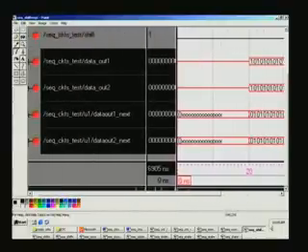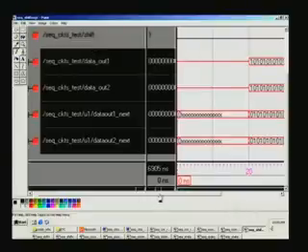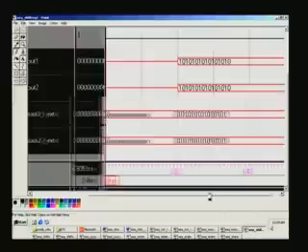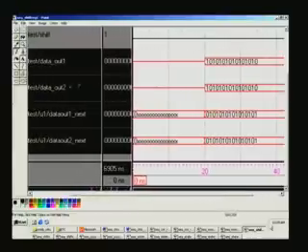So, data out is here. It is enough if you have a look at the data out. Actually we will just have one data out next. If you see, it will always pre-shift. Because it is a right shift by 1 bit, 1010 has become 0101 here, because it was right shifted. So, this will be assigned to this only with the following clock edge.